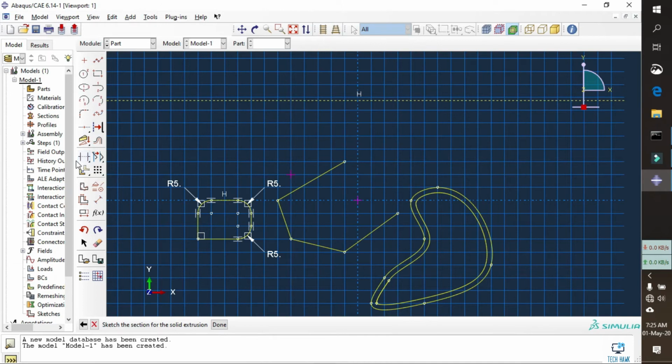So the next tool is auto trim. This is also a very useful tool. Use this auto trim tool from the Sketcher Toolbox to delete unwanted portions of any sketched edges. You can also delete this for any kind of edges, construction geometries or reference geometries. Just click here. If you click here, it will delete it, delete it, delete it, and there is no reference line now. So just click here, it will delete the whole line.